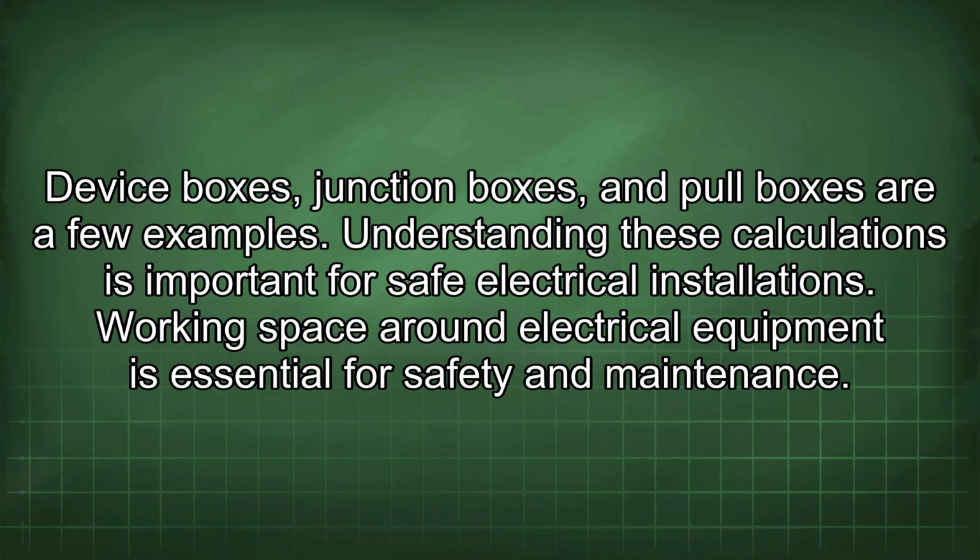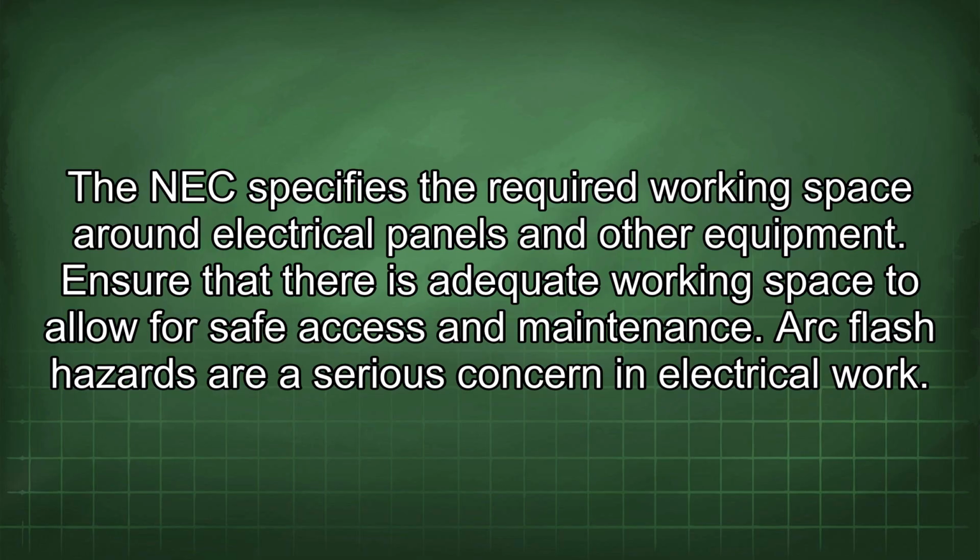Working space around electrical equipment is essential for safety and maintenance. The NEC specifies the required working space around electrical panels and other equipment. Ensure that there is adequate working space to allow for safe access and maintenance.